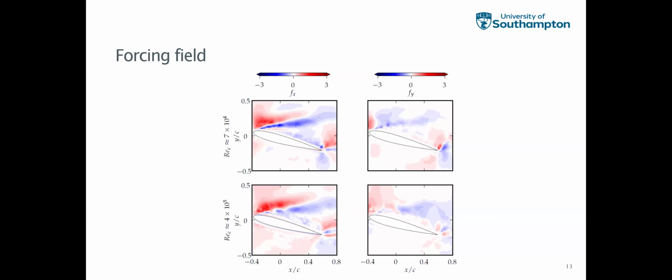And we hypothesized that there could be a universal scaled forcing field which can be applied to different Reynolds numbers of the same profile, for the same airfoil, and for the same angle of attack. This is something that we are looking into right now and it would massively help in the design of experiments. It would reduce the number of parametric studies to be performed for experiments, because it's quite an expensive affair to perform even something as simple as a Reynolds number sweep for experiments.